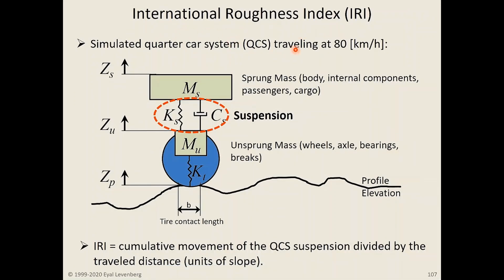The International Roughness Index concept is basically a mechanical filter. The pavement profile is the input to this filter, and the outcome is the IRI index, which provides a value that encapsulates the waviness or roughness of the tested section. To better understand how the IRI filter operates, it is instructive to evaluate its performance in the case of a sinusoidal profile as input.